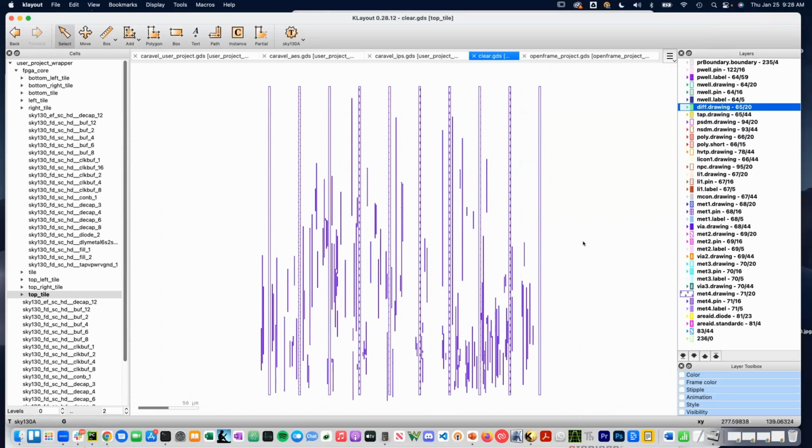There are no rings in the tile macros. There are only metal 4 stripes here, and those are connected using metal 5 on the upper level. Okay, so that's what you're saying. There are no rings implemented. Yeah. Okay. All right. Sorry, I misunderstood.